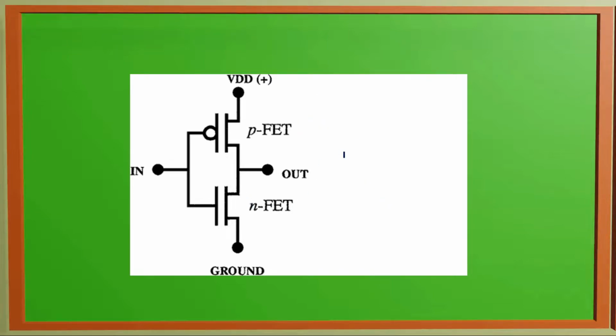So you might remember the operation of a simple inverter. If inverter input is 1, what is the expected output? It should be 0. But how exactly does it work? The top transistor will be PMOS and the bottom one will be NMOS. PMOS is also called pull-up. We have a pull-up and a pull-down transistor.